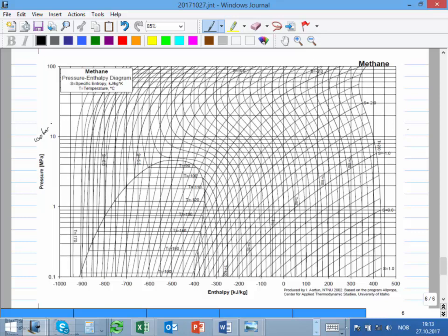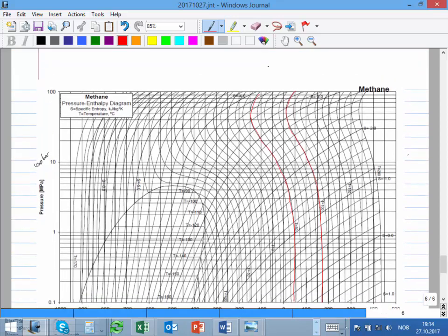Okay, and these are these lines that are like this. I'm going to paint one in red. These are the lines that have the same temperature. Okay, so this line here is 100, and this one has 50 degrees Celsius and so forth. Okay, so now let's take the point. If you remember long time ago, I hope you have a good memory. What was the wellhead pressure for the choke that we had if we want to produce 1.5 million in this intersection? You have to believe me. The available wellhead pressure was 205 bar, and the required pressure was 40 bar. Okay, it was actually the separator pressure. Yeah, you remember that example? Well, just trust me, that's the number.